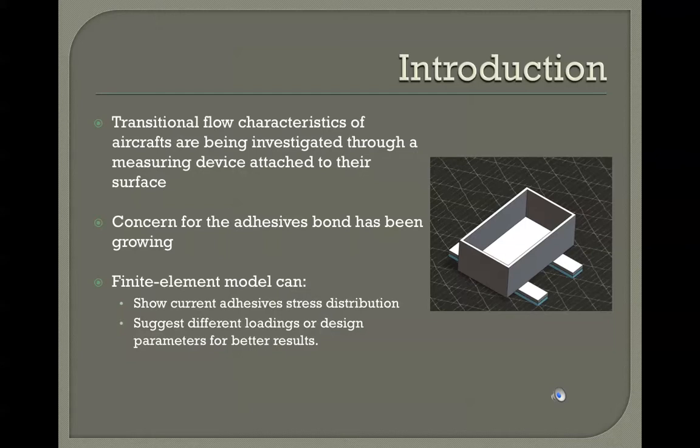Due to the electronics in the instrument, the device cannot be loaded through its middle section. Currently, the cure load is achieved through a constant compressive force of 112.5 pounds applied through a plate placed directly on top of the device. The applied force is obtained by multiplying the manufacturer's minimum cure pressure by the adhesive's applied area.